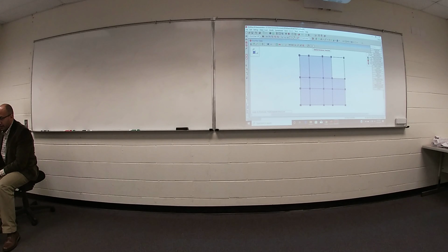So one more time, insert, loads, area load. Go ahead and choose what is the type of live load. Then you have three options how to define the area of live load. I will choose the first one, just click inside the panel. Once you are done, I'm ready.